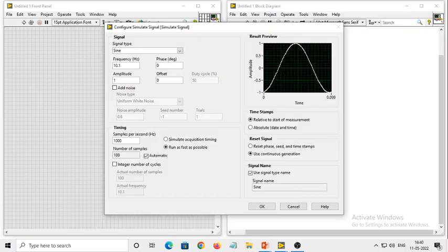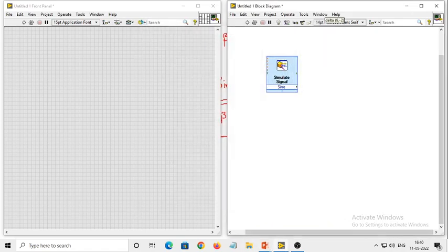Now we need to build first sine 2 pi fmt, and then we will be using a multiplier block to do beta sine 2 pi fmt. So now it is in sine, just give frequency as 10, 0 phase, amplitude is 1. One thing you need to note here is samples per second should be 10,000 and also this should be 10,000. Press OK. So this is your sine 2 pi fmt.